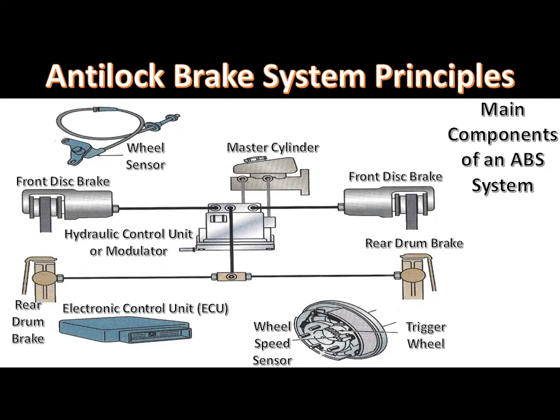It is a myth to think or believe that the anti-lock braking system will prevent the wheel from skidding. Although it does prevent complete wheel lockup, it does allow some wheel slip in order to achieve the best braking. During ABS operation, the slip will be between 10% and 20%. A slip rate of 15% means that the velocity of a wheel is 15% less than that of a free-rolling wheel at the same vehicle speed.